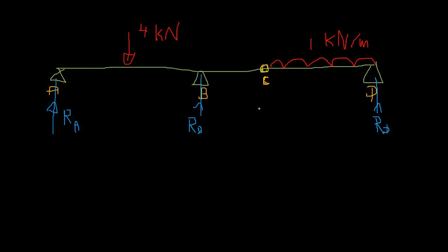So you can solve this in the first place using the hinge. So you know about the hinge. The 2 beams can rotate relatively, right? So that means the bending moment is 0. So you can take bending moments about this, since you already know the moment is 0. For each case you can take the bending moment. So for each beam you can separate it and take the bending moment, right? This is RD.